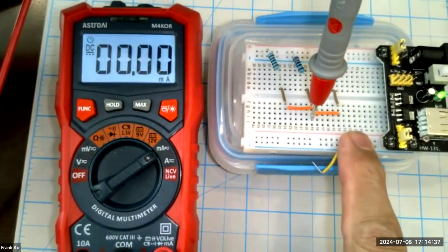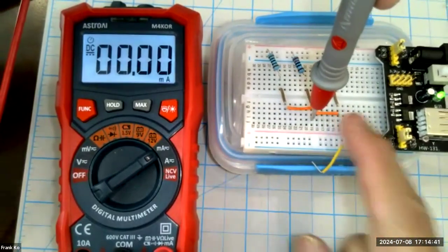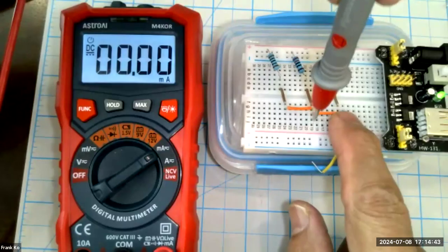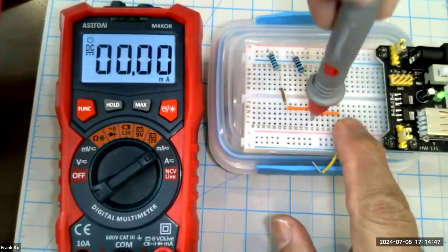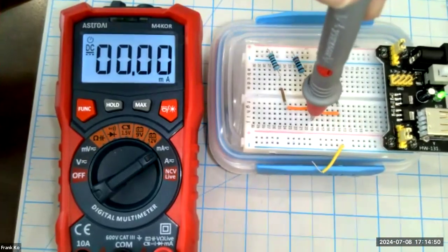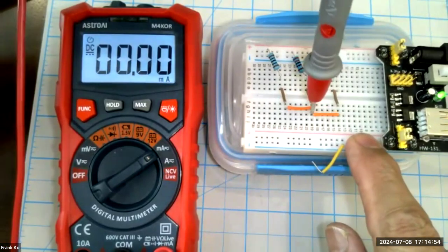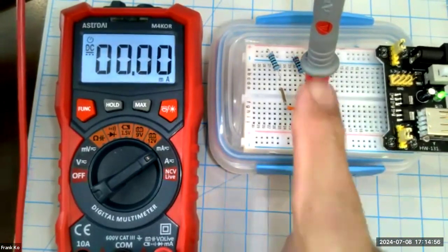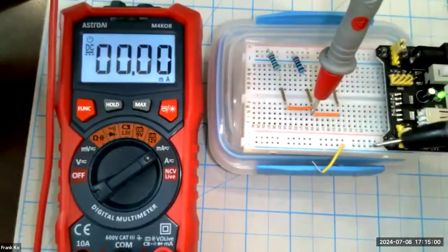I don't put it where the wire was because there's no electrical connection I can make with the orange wires. I have to touch one of the orange wires right here. Remember, just putting your wire in an empty socket does not make continuity underneath the board to the set of tie points that are consistent. So that is the positive side of the open. And then the negative side of the open is, of course, ground.